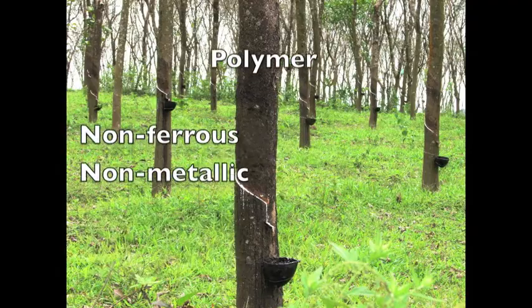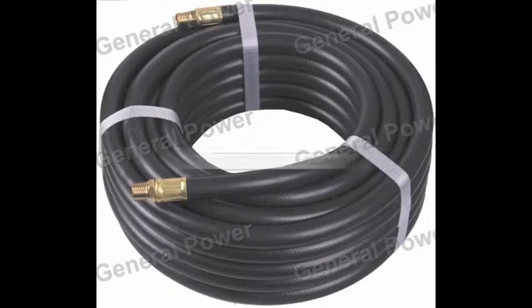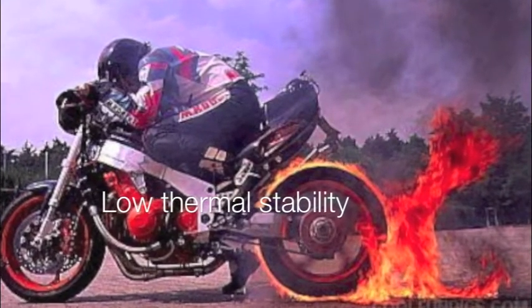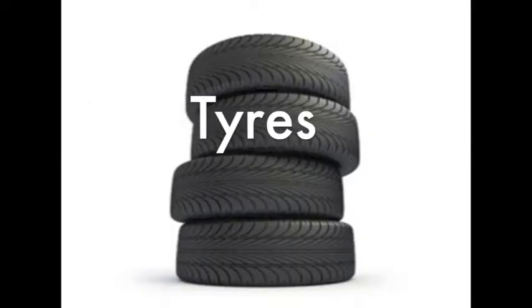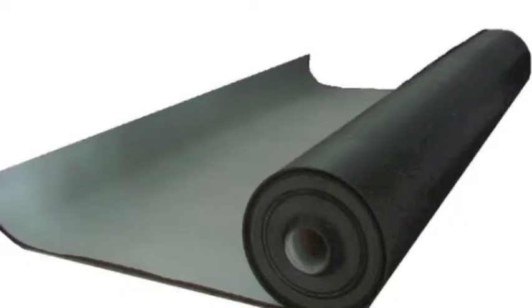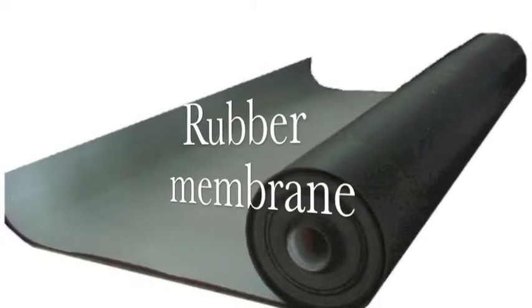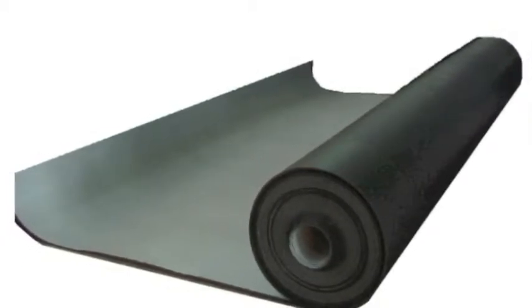Rubber is a polymer, non-ferrous, non-metallic. It's a waterproof material, insulator, flexible, ductile, and resists corrosion. It's a low thermal stability material with a melting point of 98 to 175 Celsius. It's used widely in tires, clothing, shoes, and toys. Moreover, because it's waterproof and flexible, rubber membranes are used widely. Synthetic rubber is used sometimes to enhance the properties as needed in the application.